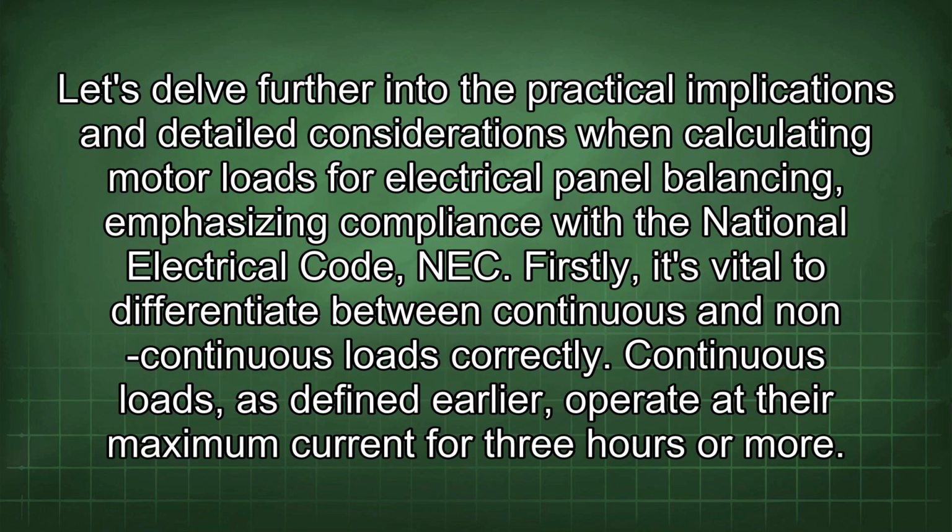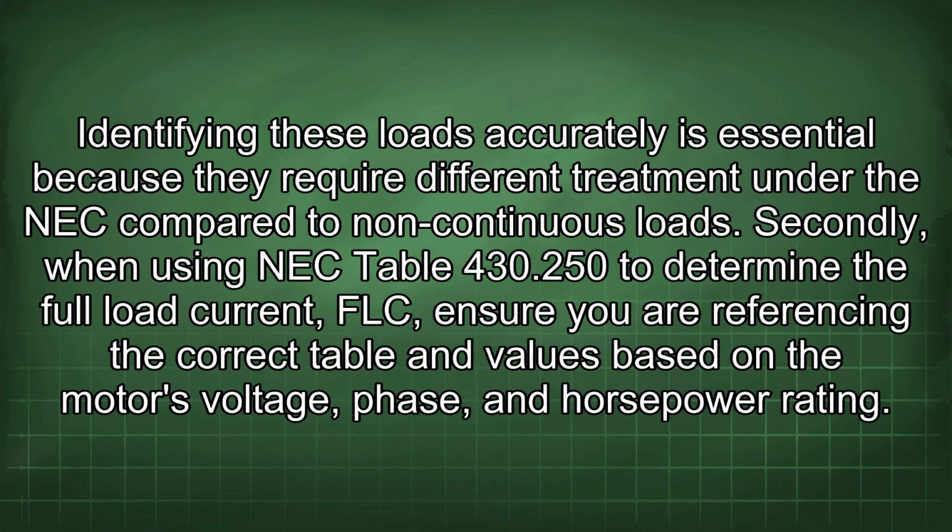Let's delve further into the practical implications and detailed considerations when calculating motor loads for electrical panel balancing, emphasizing compliance with the National Electrical Code (NEC). Firstly, it's vital to differentiate between continuous and non-continuous loads correctly. Continuous loads, as defined earlier, operate at their maximum current for 3 hours or more. Identifying these loads accurately is essential because they require different treatment under the NEC compared to non-continuous loads.